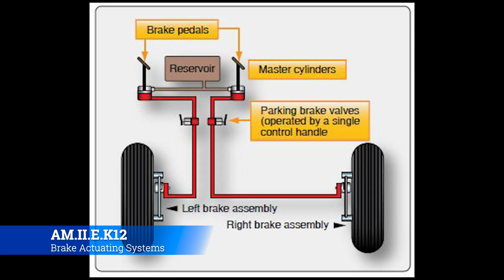Okay, so independent braking systems are probably the most common, found on Cessnas, Pipers, all your old GA aircraft, your RV-12s, all the RV series, because they are fundamentally simple. They're very basic hydraulic systems where all you're effectively employing is a master cylinder and a slave cylinder. The master cylinder in this type of braking system is almost always directly tied to the brake pedals.